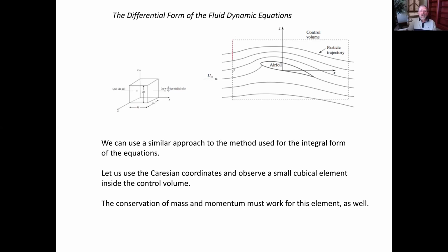We put a control volume around that. And before, what we did is we looked at the big box, the control volume, at what's happening in and out. Now we would like to develop a function, because my argument was that this way the streamlines appear to be stationary. So instead of a very complicated time-dependent problem, we can end up with a much simpler problem. But still, we need to develop a function that will describe the velocity profile everywhere in that volume.